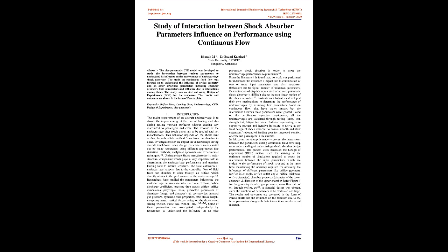The study on continuous fluid flow was focused on to understand the influence of orifice geometry and other structural parameters including chamber geometry, fluid parameters, and influence due to interactions among them. The study was carried out using design of experiments, DOE, for the responses. The results and outcomes are shown in the form of Pareto plots. Keywords: orifice plate, landing gear, undercarriage, CFD, design of experiments, oleo pneumatic.